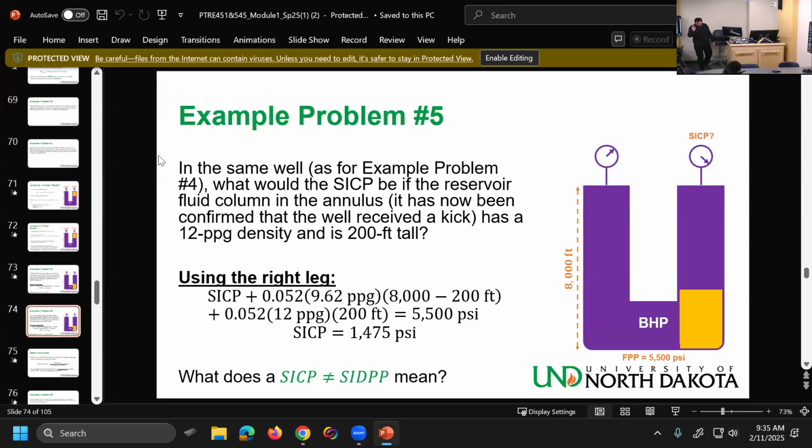We're going to go through this in more detail in module 4, but if you have been drilling correctly and you are doing it right, you can shut in the well, or you don't even need to shut in the well, you can just stop pumping, and everything will go to zero. There will be zero everywhere. That's an indication that you are doing everything correctly. Many times during drilling operations, they will stop because they think they have a kick, and they will just stop pumping, and they will see if they get backflow. And if they get 0-0, it will be fine.